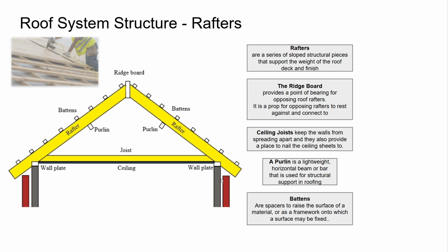Okay, so there's lots of outward sideways forces from a sloped roof, and those have to be counteracted somehow, and that's what structural engineers calculate to make sure that your roof is going to work. So once you've got your ridge board in place and your rafters, and these rafters repeat into the page every 16 inches, 24 inches, 18 inches, something like that.